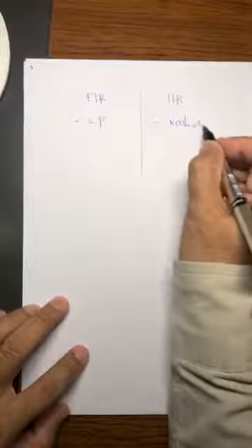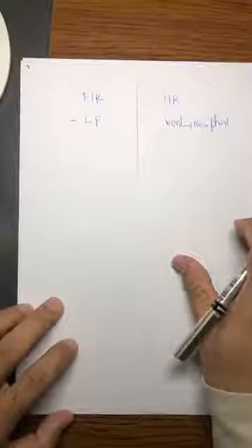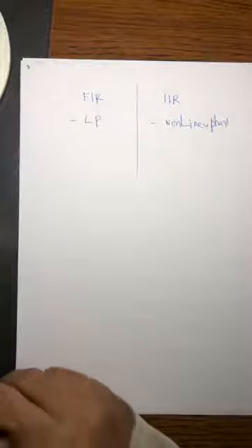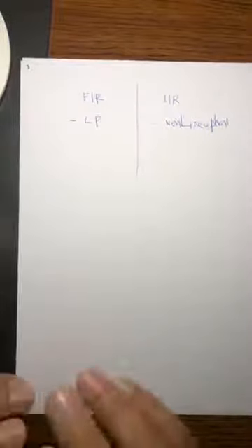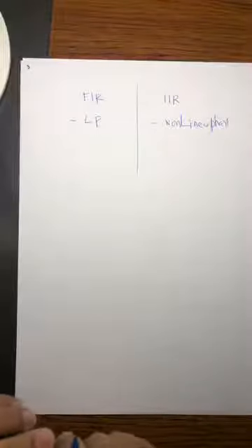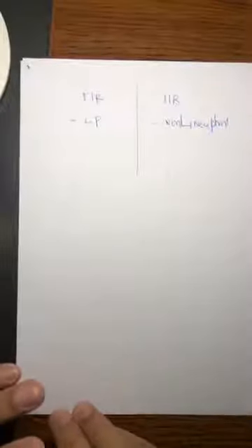But then there are ways of making it a linear phase as well, like putting in an all-pass filter. There are some techniques which help you to have close to linear phase in the pass band, and you don't worry about how your phase performs in the stop band, because those are the frequencies which you are ultimately going to filter out.